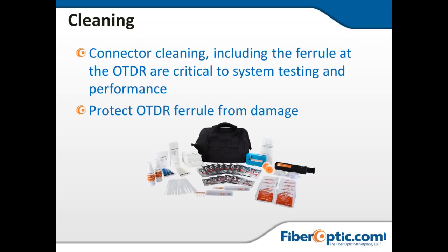Rather than just mushing it around in there and getting it to spread around on the fiber end face, it'll actually get in there and clean it and remove it by spinning. It's kind of like a dental floss, but it spins over the end of the tip of the cleaning device and also rotates around like 360 degrees. So it's spinning and advancing all at the same time, which basically causes a wiping action away and removes that dirt and debris from the ferrule. So make sure you're doing that regardless of what OTDR you go with at the end of your decision.